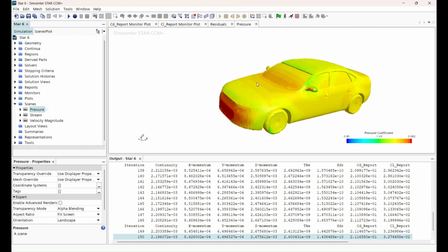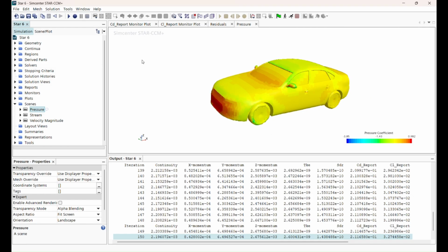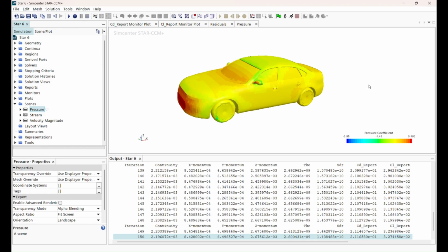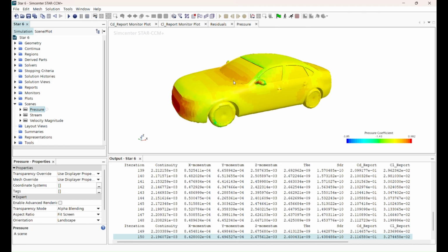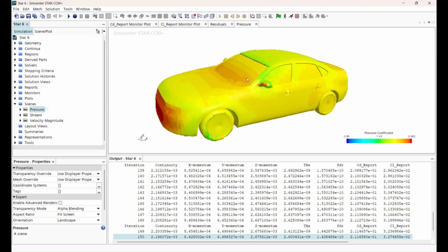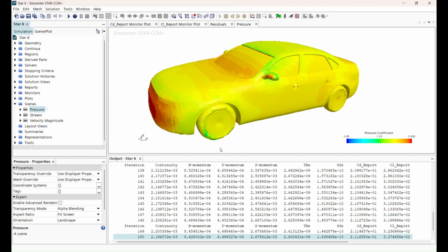This high pressure behavior in the front aligns well with physics principles. As we can see in the front of the car, we have those high positive coefficient of pressure values around 1, which is shown in red. This is classic stagnation behavior for oncoming flow, which slows to near zero velocity at the front and converts kinetic energy to pressure. For incompressible flow, which is typical in subsonic car aero, the theory essentially says the max coefficient of pressure is about 1 at the stagnation point. So these results align really well with physics, as it's the high pressure right where the air hits the nose the hardest.